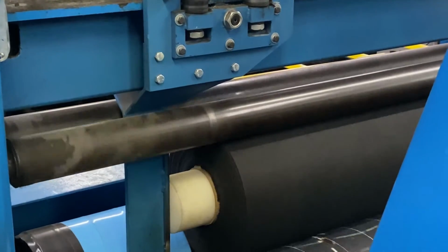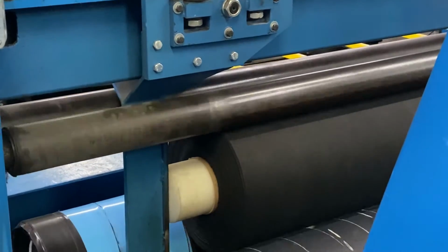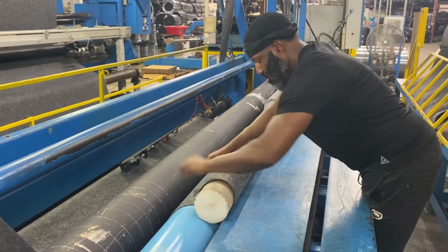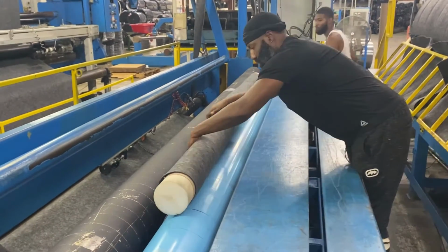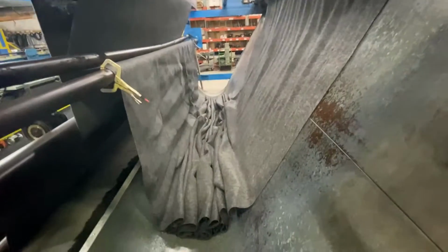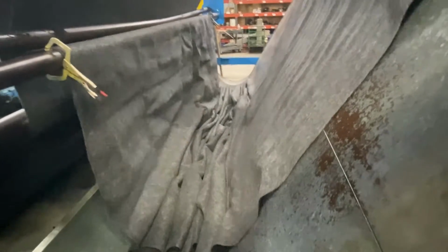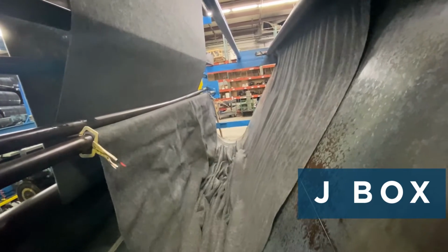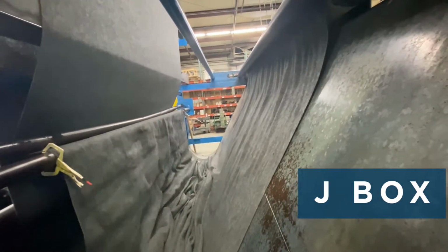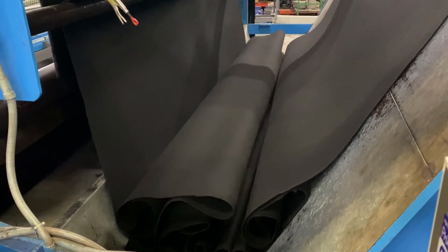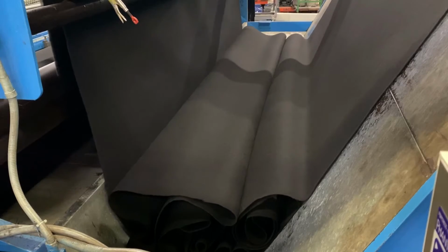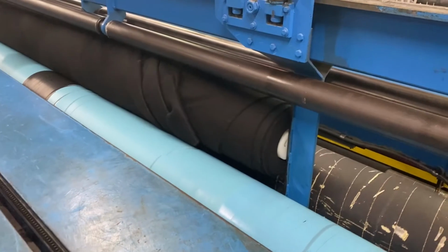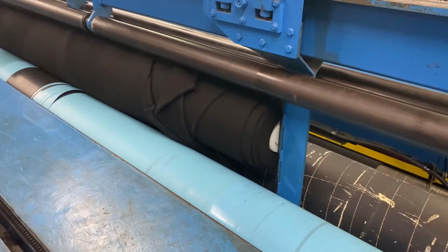You are now ready to build a roll. The rest of the line will already be running while the winder is stopped and the roll changing process is taking place. It is important to be as timely as possible during this roll changing stage because the material is accumulating in the J-box while giving the winder employee time to complete the steps. However, if too much fabric collects in the J-box, it could potentially create trimming or roll build issues, which will make the roll off quality and shut the entire line down.